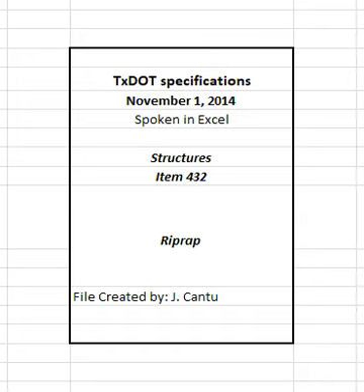Based on a specific gravity of 2.5 and using the following equation for the intermediate axis diameter: D equals 12 times (W over (GS times 62.4 times 0.85)) to the 1/3 power, where D equals intermediate axis diameter in inches, W equals weight of stone in pounds, GS equals specific gravity of stone. Note, if the specific gravity of the stone is different than 2.5, then the above equation can be used to determine the appropriate size using the actual specific gravity.